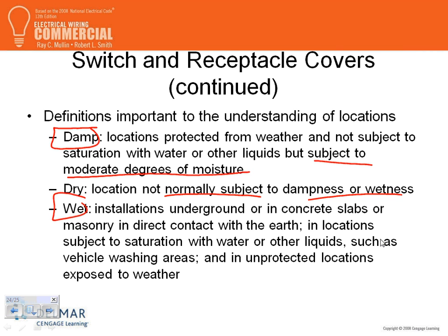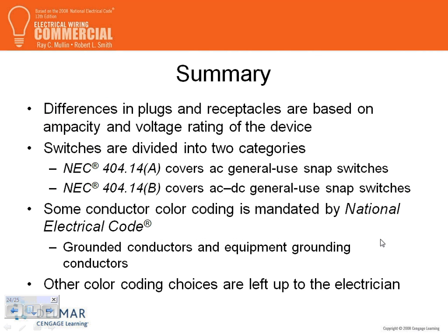Any questions, guys? Why do they define this? Because in these locations you need a weatherproof receptacle. The inspector will catch you on that one. A weatherproof receptacle with a cover, a heavy duty cover, based on 2011. Heavy duty cover. Any questions, guys? This is what I thought was interesting to cover. Any questions about that?